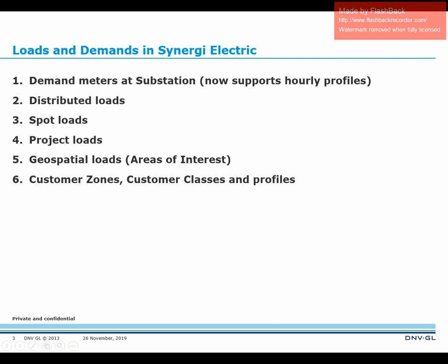We also support distributed loads, which are on the section model, and I'll open up Synergi and show you that. Spot loads are also on the section. We support project loads, which are more speculative loads, maybe new construction, new development that you know about, and you want to track these loads by name. We also support areas of interest, which are spatial polygons that you can assign either an absolute load value, or you can also assign a load growth.